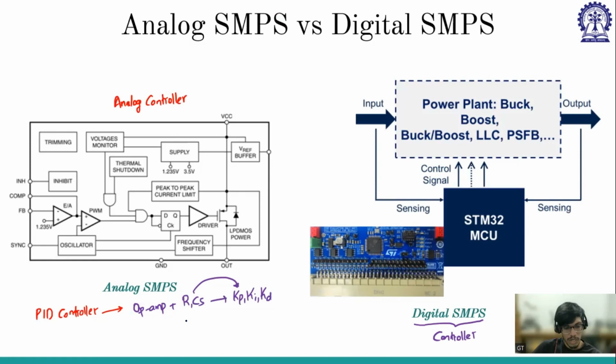Say if you got some X ohm, you have to see whether that X ohm is actually available, or if it is not available, then you have to adjust with a nearby resistor. It cannot be exactly that particular resistor value till the decimal point, so we'll get nearby KP, KI values.